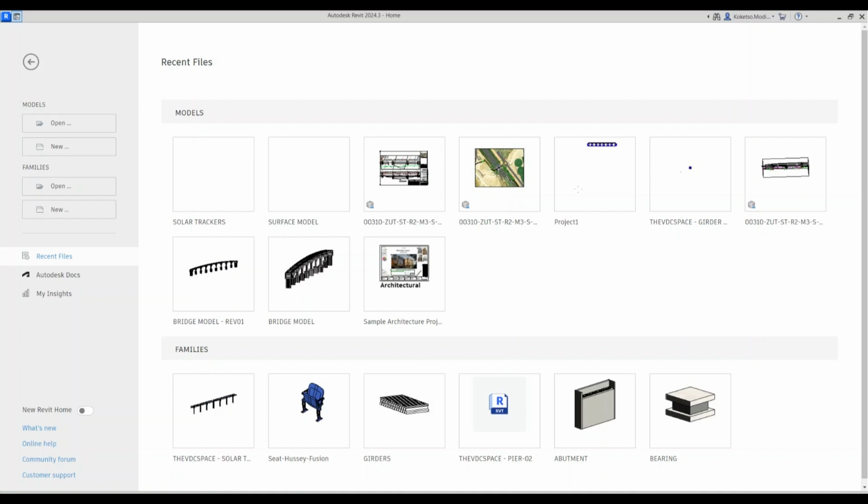All of that is consolidated and placed together in a master information delivery plan. So the TIDP and MIDP are among the major BIM requirements whereby a project is executed using BIM implementation or ISO 19650 standards.